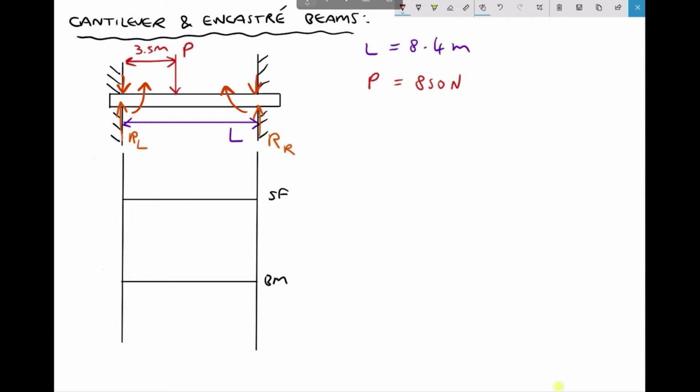The first of these equations is as follows. RL, the left-hand support reaction, equals the force times (3A plus B) times B squared, all divided by L cubed. Now, this is a standard formula, but we need to take a bit of care here because our point load F, given in the equation, is actually P as specified on our diagram. So P and F here are interchangeable.